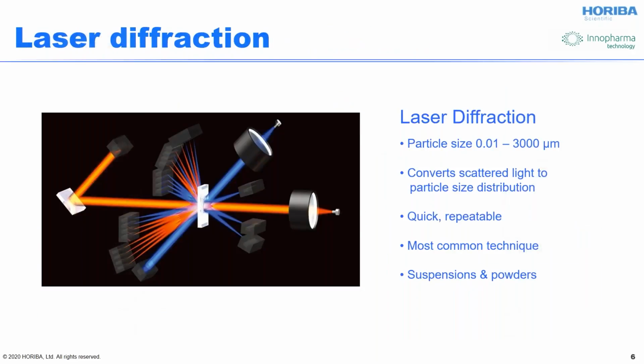The next analyzer down in particle characterization, so kind of looking at what else is at the edges of image analysis, I would talk about is laser diffraction, which reaches from tens of nanometers up to about 3 millimeters. Now, I'll tell you, imaging is a whole lot more fun at 1 millimeter and up compared to laser diffraction. So, there's some crossover, but there are preferred operations for both sides. It looks at scattering as a function of angle to get the size distribution. And it's very common, which is why I mention it, and it's very fast and repeatable.